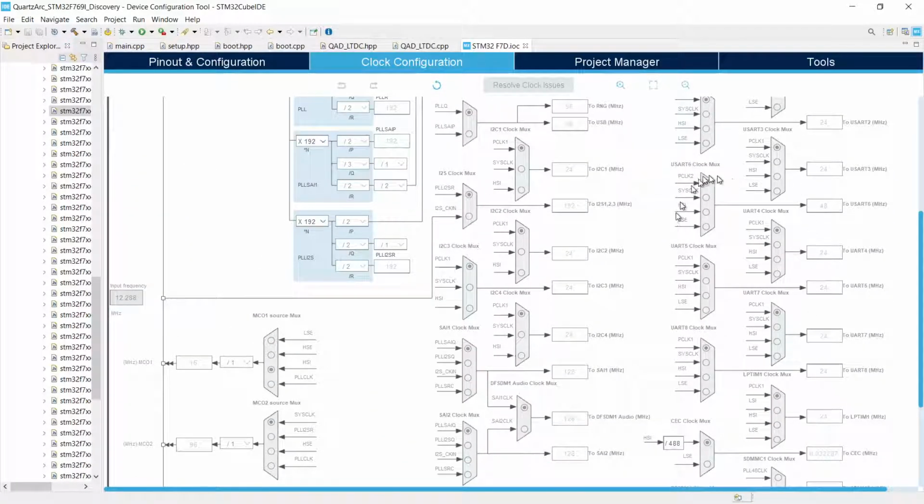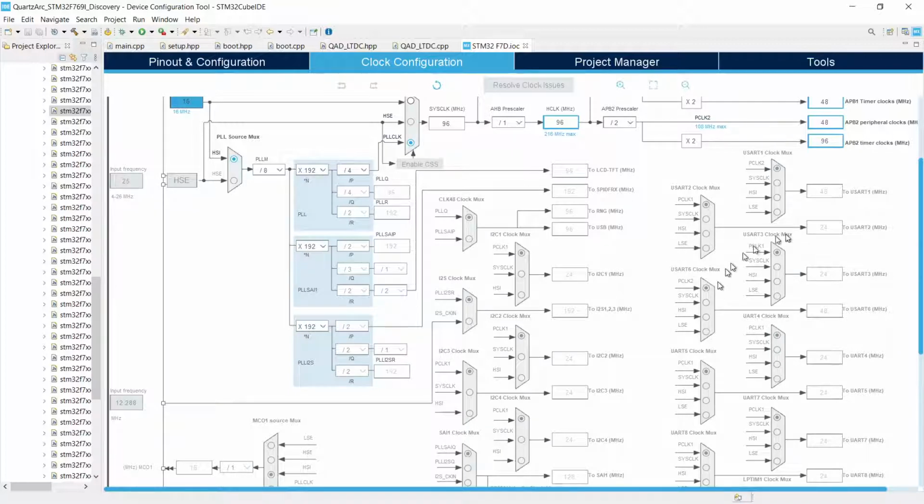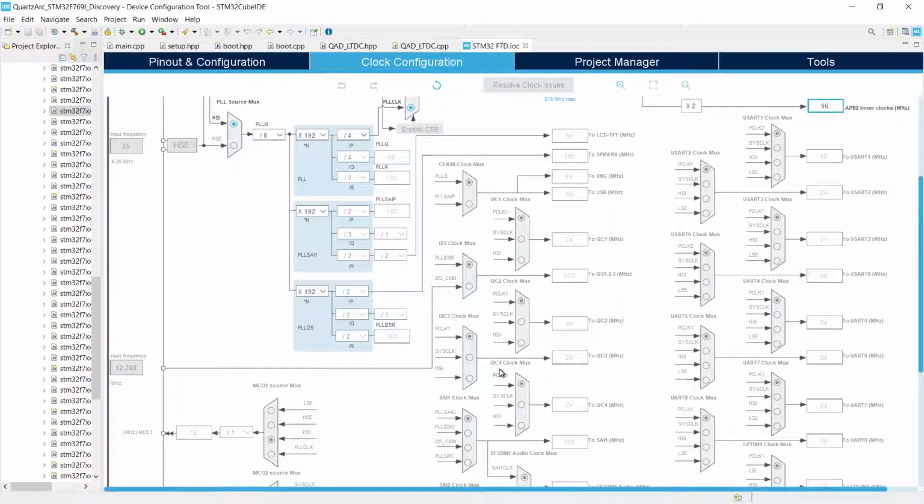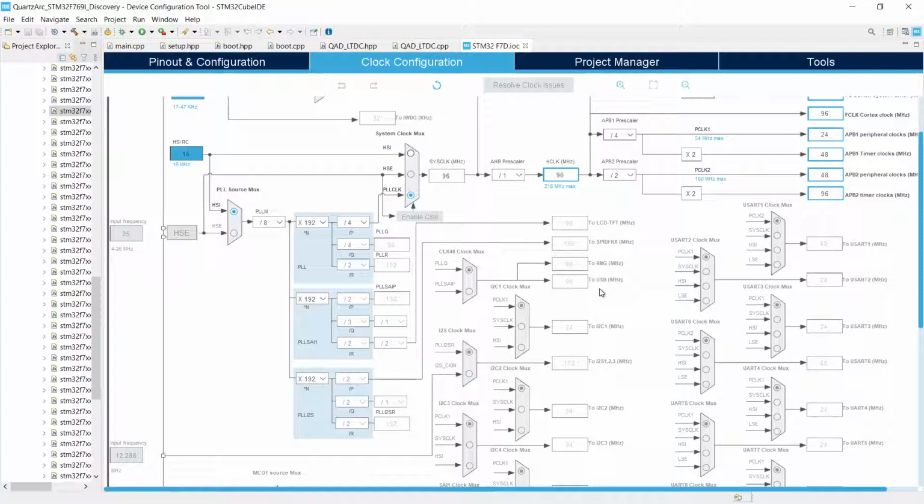And this one does give us a lot more options as to the particular clock sources that we're using for specific peripherals. So definitely a lot more configurability here. And depending on how you go to set things up, you may need to be aware of making sure that certain clocks are set at a particular value in order for things to work correctly. So for example, with a project that I'm doing with the F429 at the moment, the main requirement in the clock setup for that is that the USB peripheral is getting a 48 megahertz clock, because we need to use that peripheral. That's the clock that it needs, which means that everything else as far as setting up CPU and bus clocks, stuff like that, kind of revolves around making sure that we're getting 48 megahertz to the USB, and then we can configure everything else to fit within the parameters we need there, but still give us the levels of performance that we're looking for.